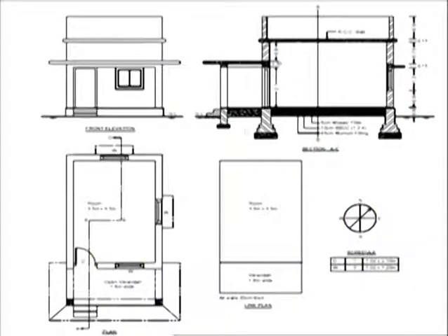how deep it is going. So this is the veranda wall, because here also we need the wall. If you do not provide the wall here, this soil, because the height of this flooring is higher than this ground level, it's called the plinth height, has to be confined between the walls.